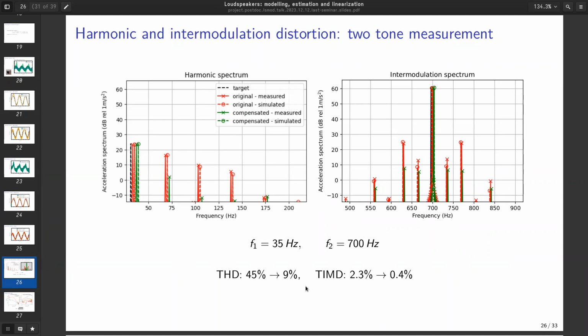And Finn has a comment to that. It's definitely more important to get rid of the intermodulation. Harmonic distortion on its own is quite difficult to detect, because most signal material, most music will have harmonics already there, right? So you don't really notice that so easily. But the intermodulation is what's important to get rid of. But is it enough to get down to 1% or 0.5%? I don't think there's a clear answer for that, still.